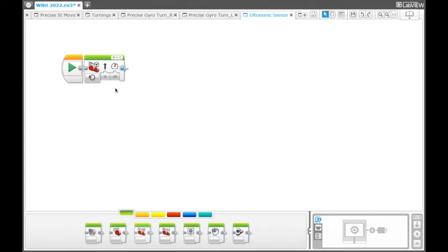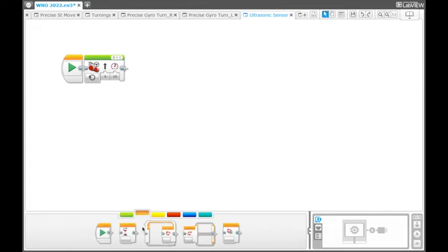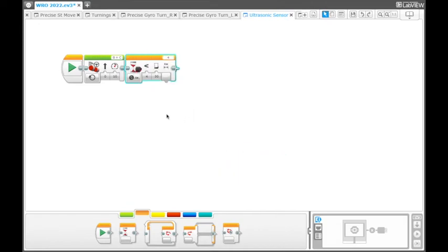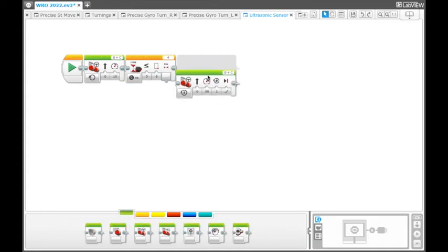So I'm using power 10 only for now, and then you can use the ultrasonic sensor. It is based on what distance there is between the ultrasonic sensor and the object, and also it depends on where you are connecting the ultrasonic sensor on your robot. So in my case I have used distance 8 in compare mode, in centimeters, so it will be less than or equal to 8, and then you can stop the robot there.